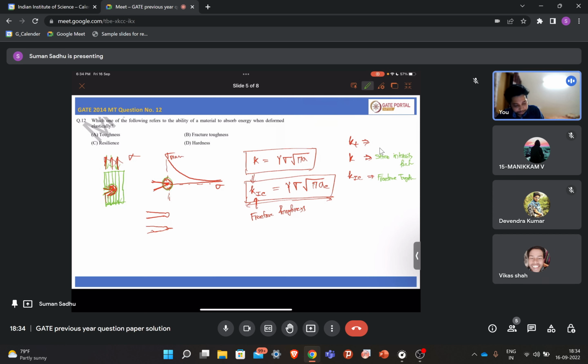So it is the ratio between this maximum stress and this sigma. So KT is sigma max over sigma. What is KT showing? KT is showing what will be the stress concentrated near your crack. This ratio defines how much stress will accumulate near the tip of the crack. So it is called the stress concentration factor.